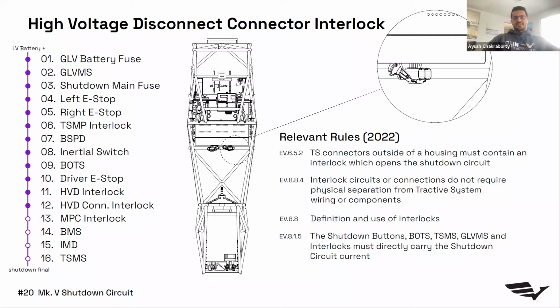Something you brought up was that we can't have any firmware in the BSPD. If we can't have firmware there, how do we stop requesting torque from the motor controller? How do we send that signal? Is that different? Yeah, good point.